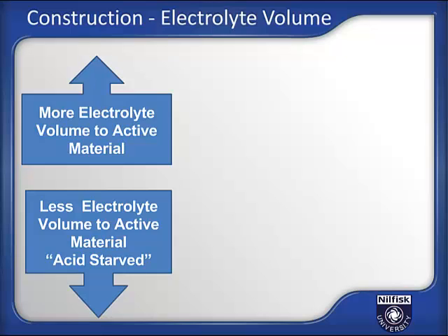That is to say that enough electrolyte is in the battery to create a reaction, but you're not completely immersing the plate in electrolyte, such as in a flooded battery. So the term acid starved can only apply to sealed deep cycle technology where the electrolyte is not in a pure liquid state, or it's immobilized.